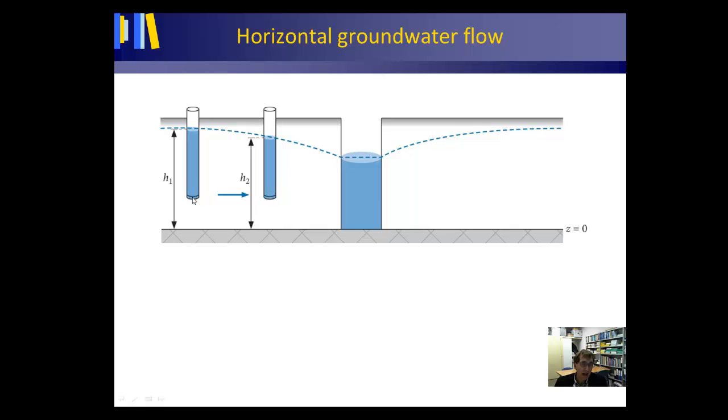So here we have a higher hydraulic head, a higher total energy than there, meaning that water is flowing in the direction of the lower hydraulic head H2, and that in actual fact, if I come back to the earlier multiple choice question, the right answer must be that water flow is from a high to a low energy, from a high to a low hydraulic head.